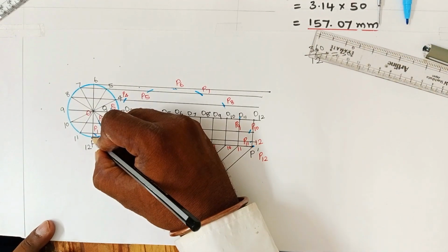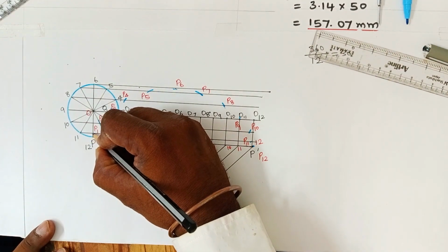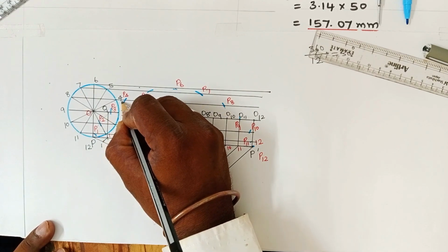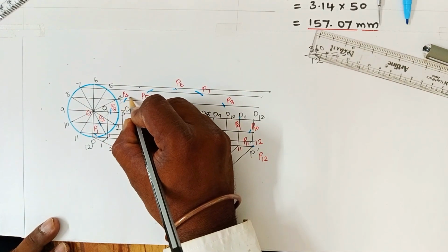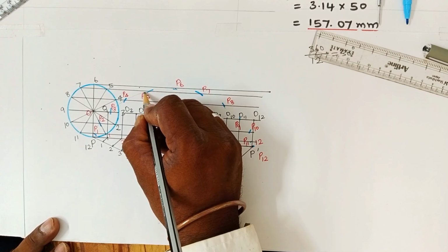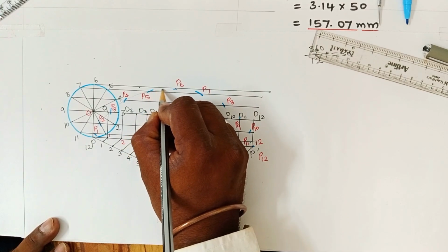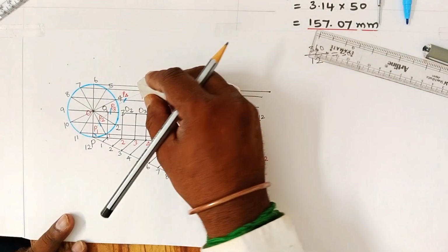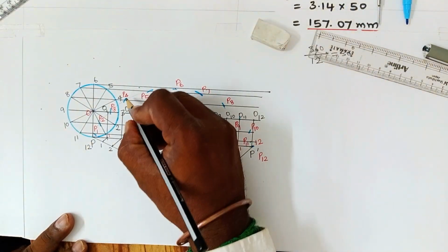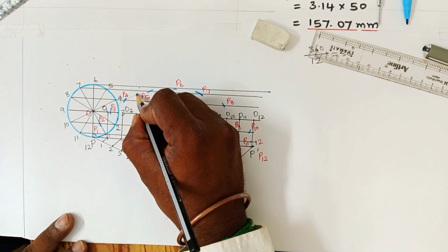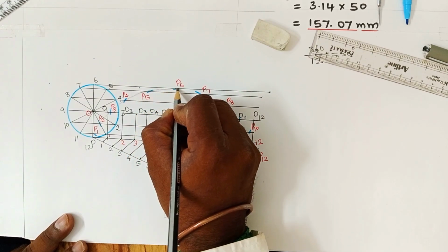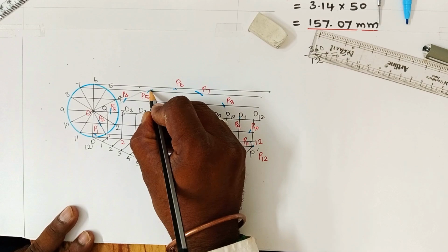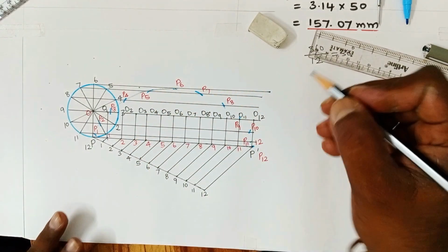Draw a smooth curve passing through these obtained points starting from letter P. So join P with P1. First you draw a lighter line. Your hand should bend. Don't use a scale for this. It should be a freehand curve. Gradually it should be turning. Don't turn your drawing board or drawing sheet. Draw a smooth curve passing through these. If the curve goes cross, then you erase that part and correct it. Don't paint the curve. It should be a single stroke or single pass.